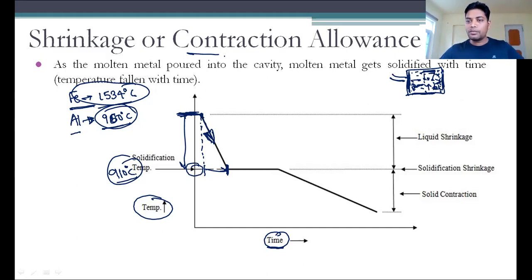So as it becomes semi solid at the boundaries, it will show you this figure. Okay, from this to this, initially it was completely liquid and it starts to become semi solid, and as it becomes semi solid, this semi solid formation moves towards the center. Okay, so from here to here, all the molten material will try to become semi solid inside this space, or mold cavity, we can say.